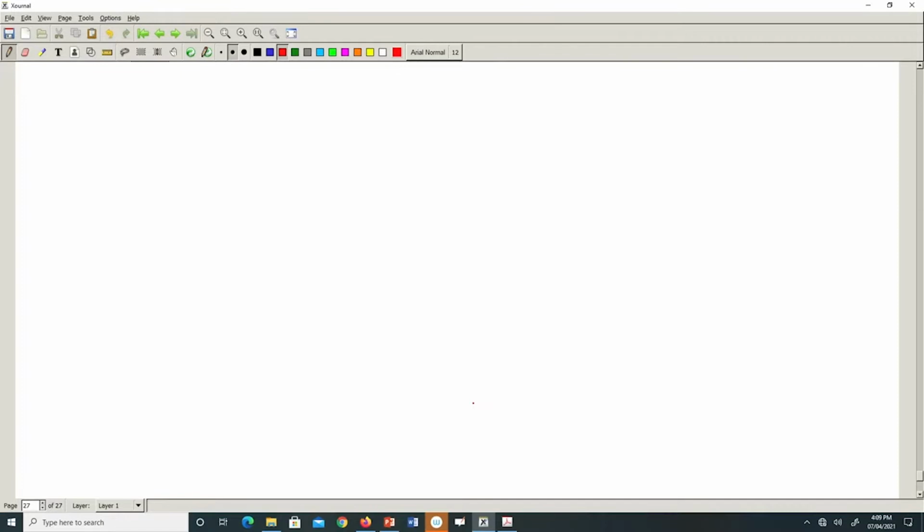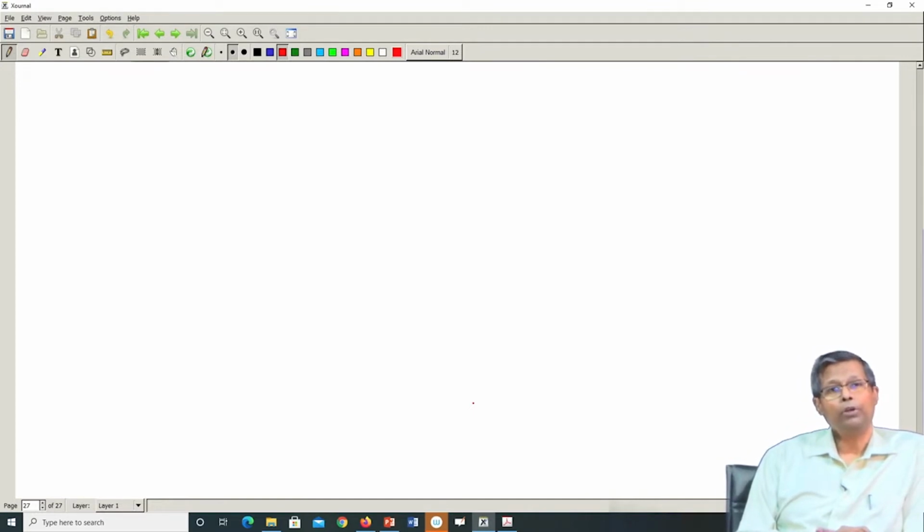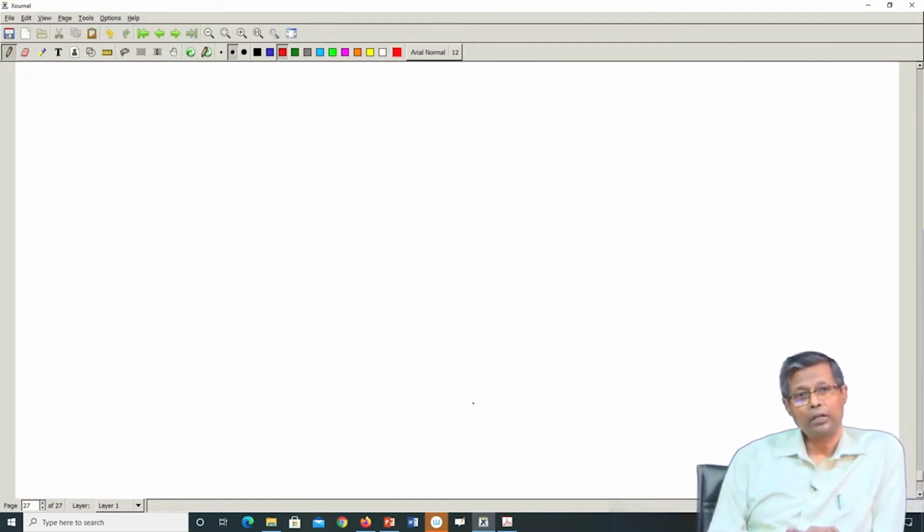So, we saw previously that in order to find out the amplitude of the nth forward moving wave inside a rectangular waveguide, we invoke the test mode, the second set of fields, which involves the nth reverse going wave.